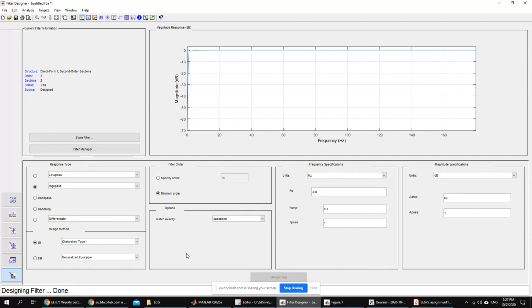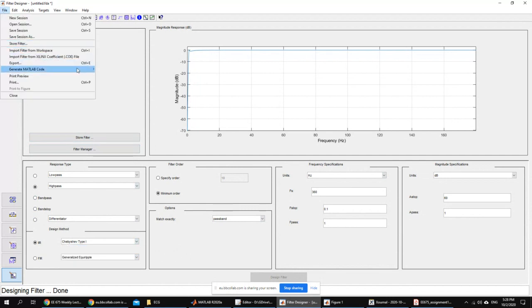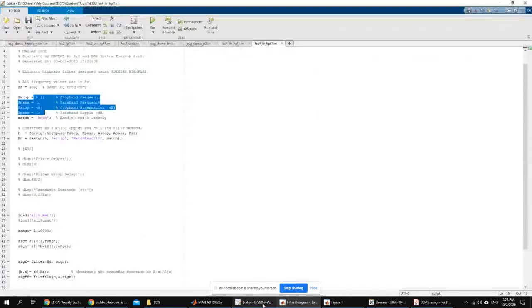Okay, so this is for the IIR filter. Do you have any problem with the IIR filter optimization? Again, we're going to start with the type of filter we want, put the parameters, and then choose different types here until we get a type that looks like it's giving us the best performance in terms of the order. And then generate the filter design function, go to it and see the performance, make sure that it works, and then tweak the values for the f-stop, f-pass, a-stop, a-pass, until you get something that looks as good, but with less order.